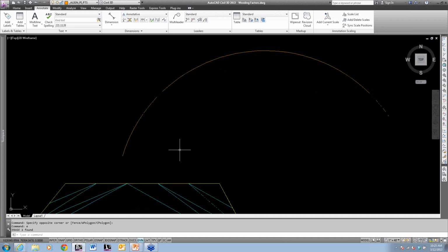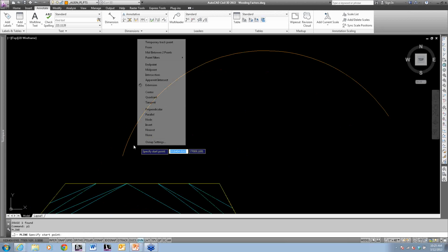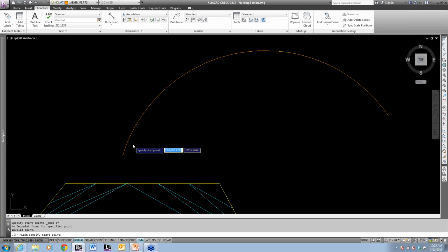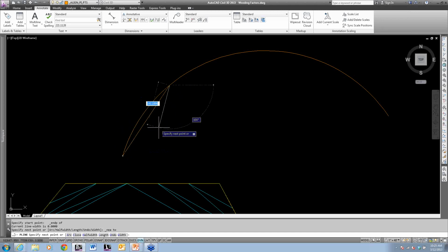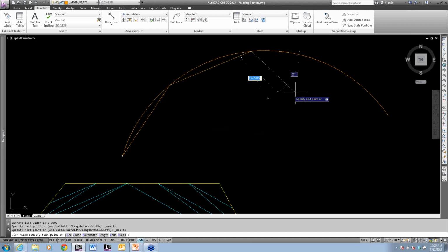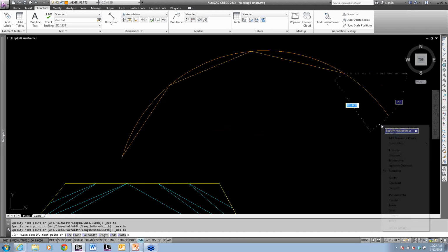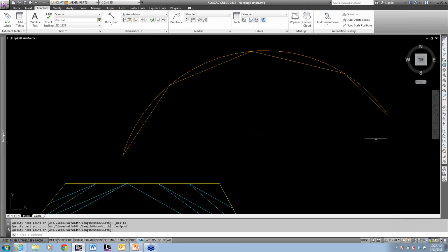Basically what this does is it says, let me start at the beginning of the curve here. Civil 3D is going to start running a line along the curve until, right there, I've got a mid-ordinate distance of whatever value we set. And it's going to continue along and say, right there's the next point, and right there's the next point. These are the points that actually end up getting added to the surface when I have a curve. So the smaller the mid-ordinate distance is, the more data we're going to be adding to the surface.